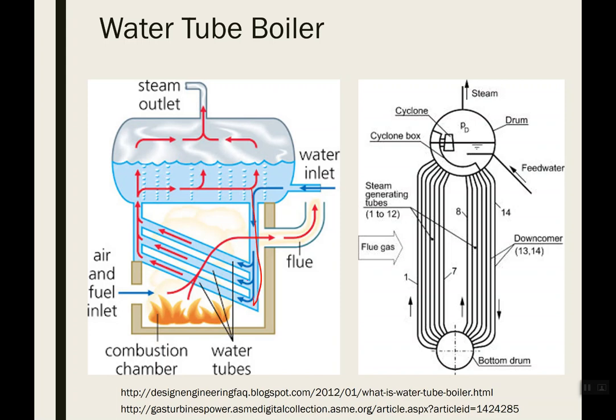And then you have these tubes come down. This is called a downcomer, and this is called a riser, and that water is going to circulate through the boiler. Basically it's actually a water vapor mixture. This water vapor mixture will come down, pass through the firebox of the combustion chamber, where it's going to have heat added to it.